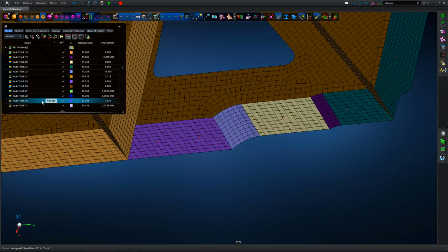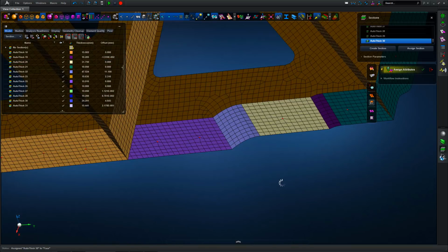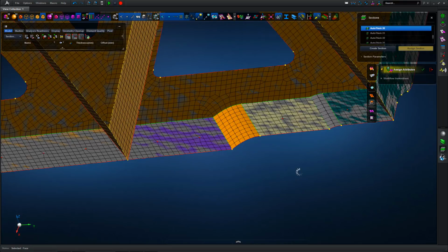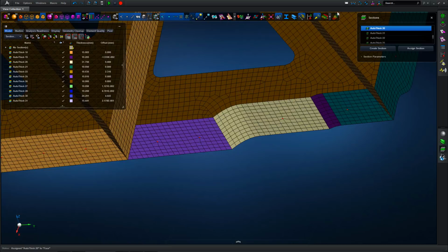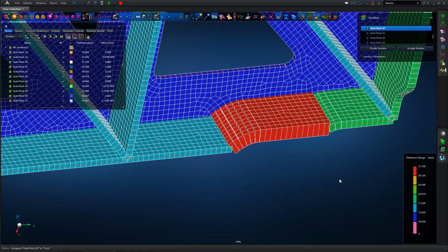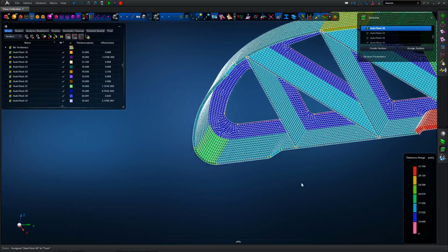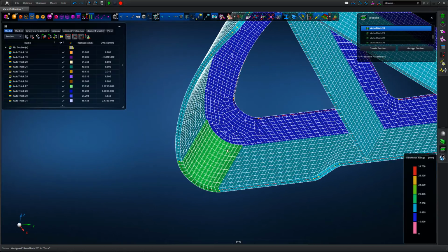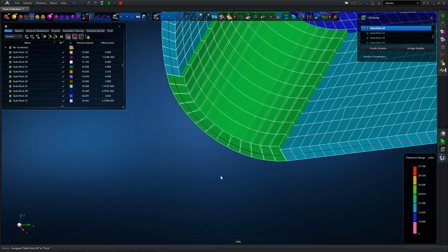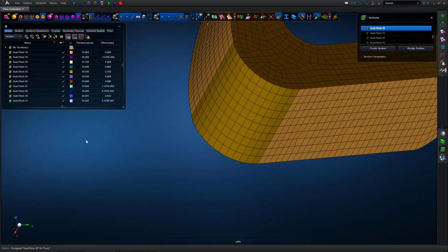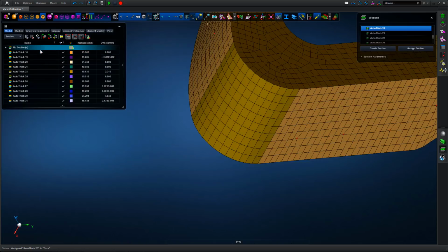We're going to match up the joggle with the yellowy brown surface, and then define that on the step joggle surface. Again, trivial to highlight and update, and we can see the 2D thickness is updated as we require for those updated regions. So finally, we've just got a region on the nose of the rib.